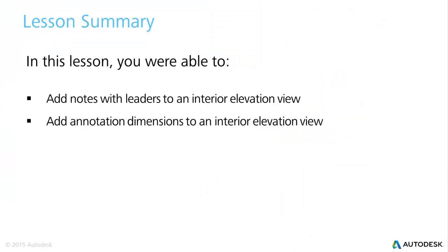Let's review the learning objectives for video 9. In this lesson, you were able to add notes with leaders to an interior elevation view. And then we completed that elevation view by adding annotation dimensions. So it's all ready for placement on a sheet view. With that, let's take a look at Autodesk resources that are available to you.